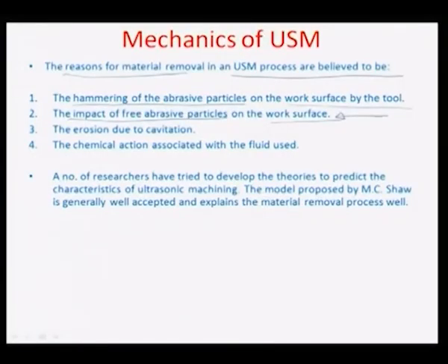Then of course there is the effect of erosion, which principally comes from cavitation. Now I would like to explain a little more on cavitation. Whenever there is a high frequency object, say a surface which is moving at a very high frequency with a fluid resting on it, the fluid, because of its very large inertial component, may not be able to move at that higher frequency.